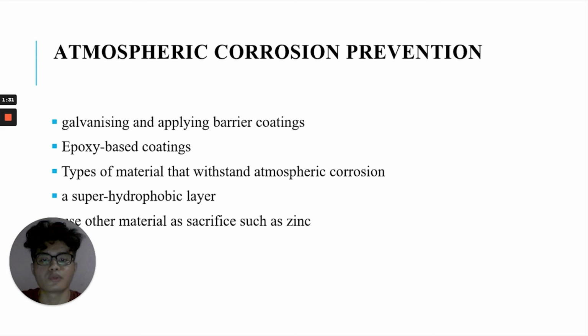The following two characteristics are advantages of covering with a super hydrophobic layer as a defense against air corrosion. Water droplets touch a super hydrophobic film through a composite air-solid interface when exposed to atmospheric conditions, where air is trapped in the film grooves.